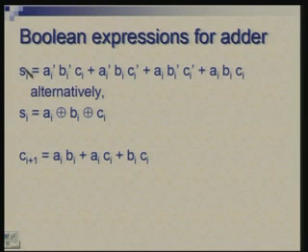So, in the current design of the adder which we have talked of, you could imagine that the delay of each 1 bit adder can be brought down to 2 times d. Okay. You can always express that as we did earlier, as we have shown here. We look at this realization of S_i and C_i+1.